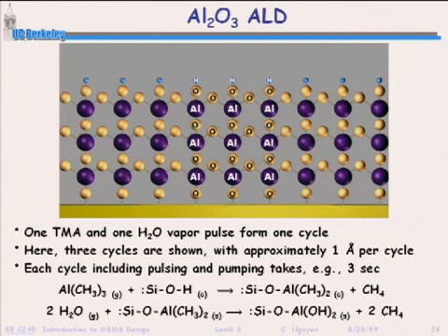complete. I mean, it looks like it's single crystal at this point here, but it really is an oxide that's growing up. I don't think it's that perfect in the end, because I know that you can get variances between different ALDs. Alumina is pretty good. So with alumina, I'm kind of hesitant to answer that, to say that it's not really single crystal, because it actually is pretty good. But definitely with other ones like titanium dioxide, hafnium dioxide, at least when we've tried it, we don't get a consistency that tells us it's single crystal.